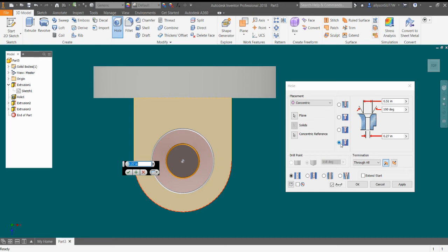So we have the dimensions for the counterbore. And so this needs to be changed to 0.44 inch. I'm sorry, I have this on countersink. So glad I looked at it. And the reason I know that is when I look at my directions, the picture does not match what I have on my screen because I was in countersink and not counterbore. So now that I'm in counterbore, I'm going to make sure that my dimensions match up.